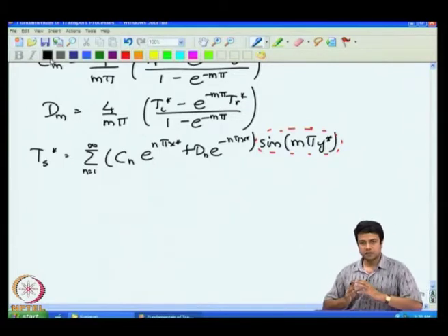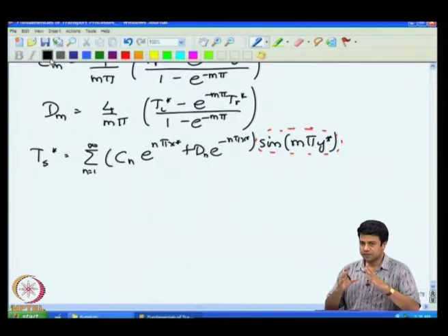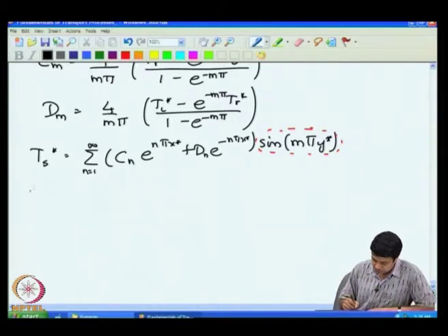So, for the unsteady part, we will be using separation of variables once again. But whenever we do separation of variables, we have to ensure that there is only one inhomogeneous direction, that all other directions are homogeneous. If all other directions are homogeneous, then we will get eigenvalues and basis functions in all of those directions. There will be one inhomogeneous direction where the initial condition or the boundary condition will end up forcing the profile.